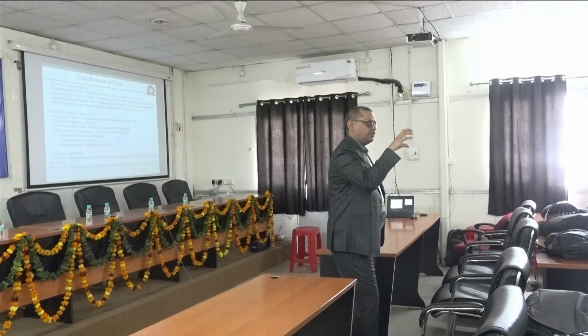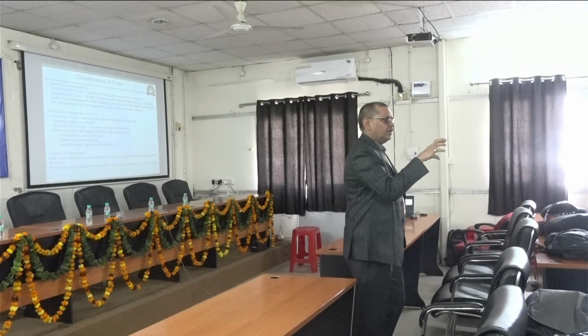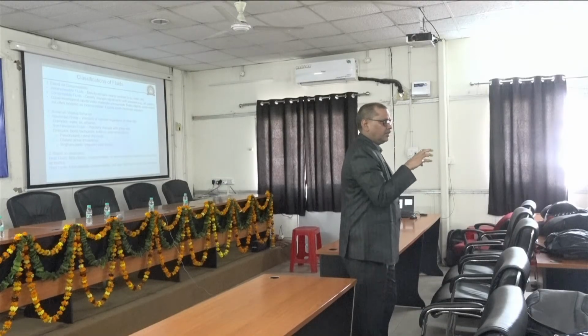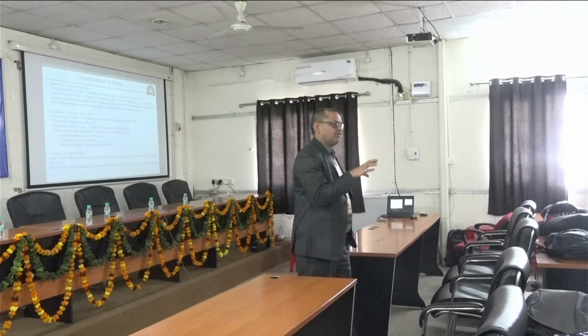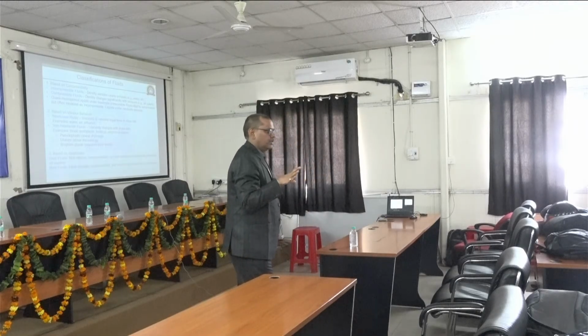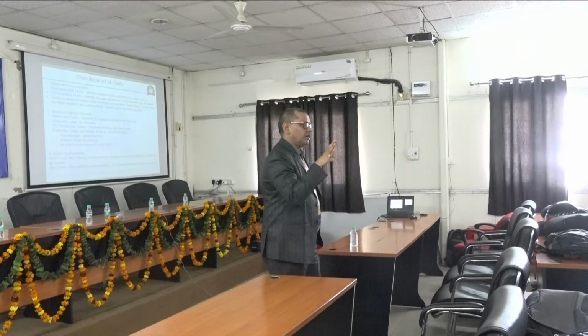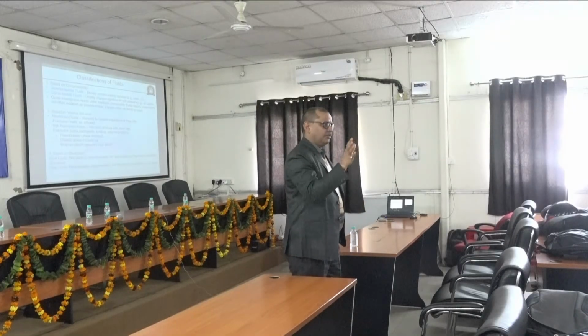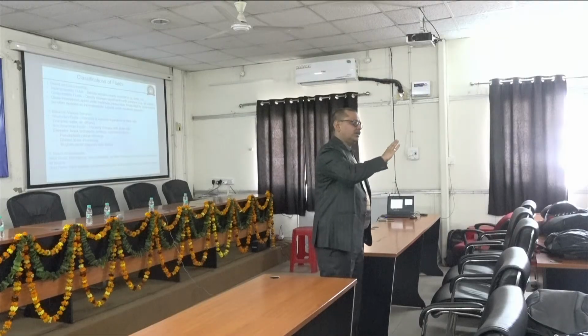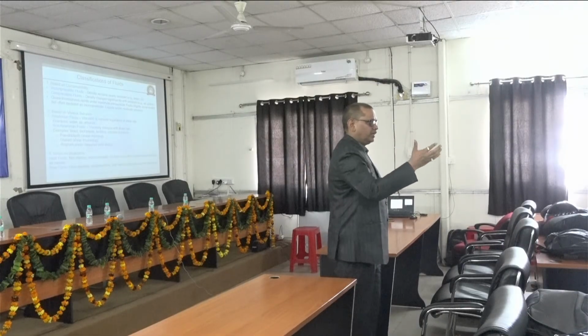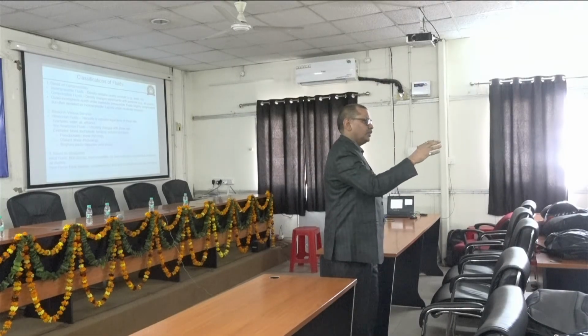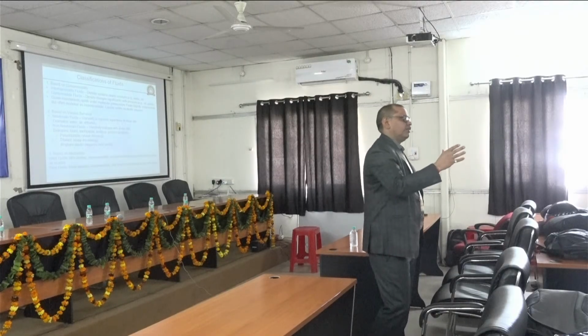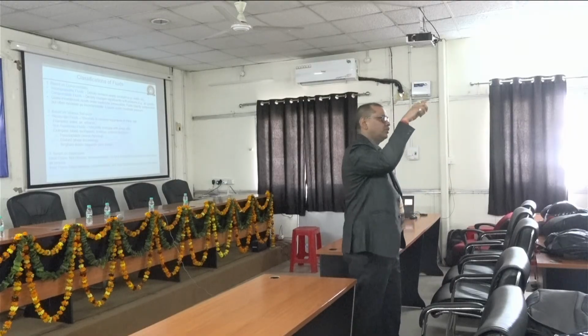The viscosity of the fluid will be measured by the viscometer, and this viscosity represents how viscous the liquid is in nature. So based on that viscosity, you can define the fluid as Newtonian. If deformation is not linear, if deformation is non-linear in nature, like when you apply the force and the deformation is non-linear, how can you define it mathematically? You can define that tau is proportional to gamma dot to the power n.